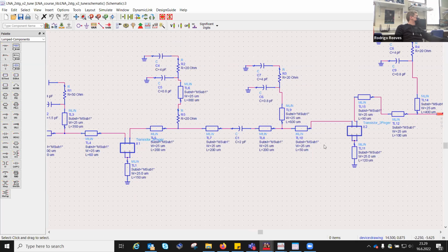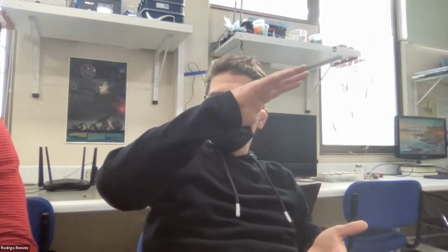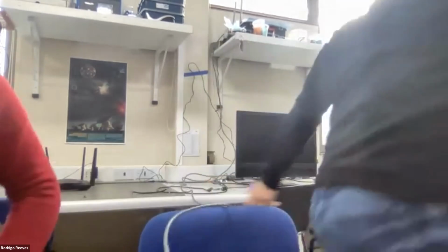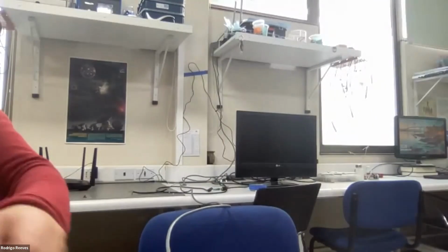More or less this. But this new resistor that you have, yeah, you can try to add it there. What's the reason for that? The stability? Yes, that affects a lot of the stability. But you need to have a longer shunt stub to make it close to the quarter wavelength, right? Yeah. Okay. The problem is when you did the optimization. I didn't optimize, I did tuning. Yeah. Okay.